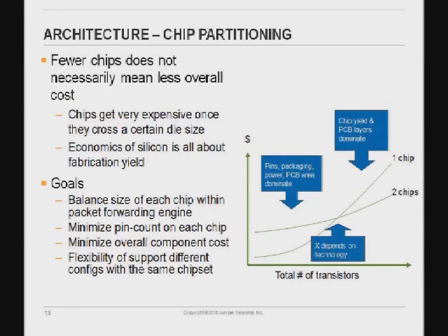So designing multiple chips might be more advantageous as a total system solution, splitting the logic into different ASICs. So the goal is the overall system cost instead of just the chip cost itself. And again, even the chip cost itself might dictate you to split them because of the yield issue.